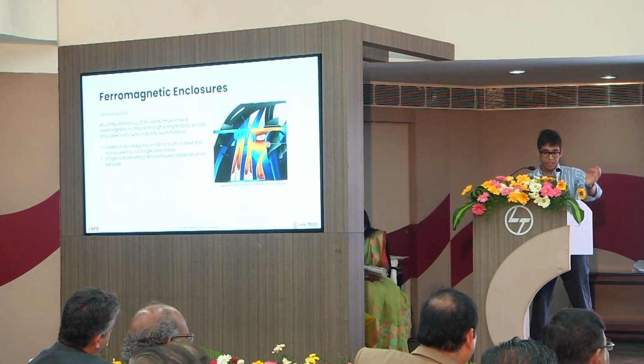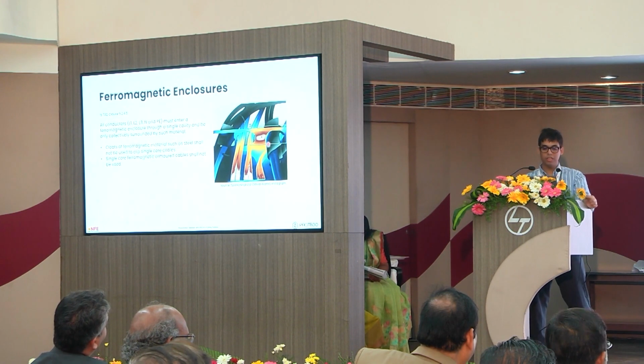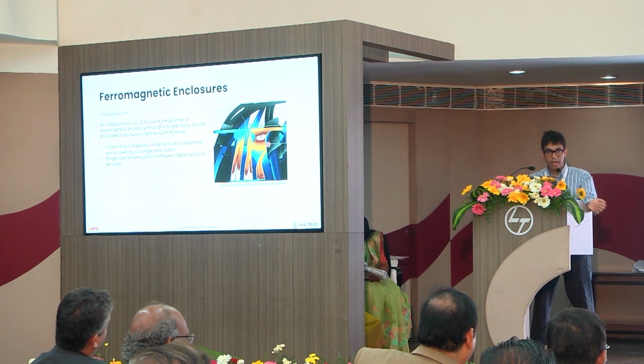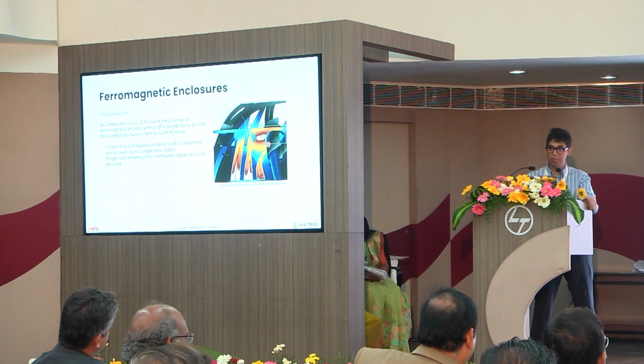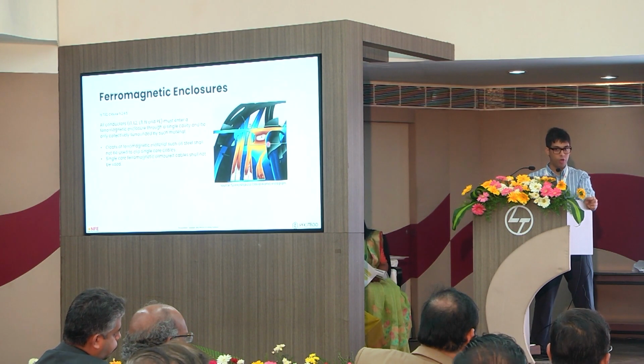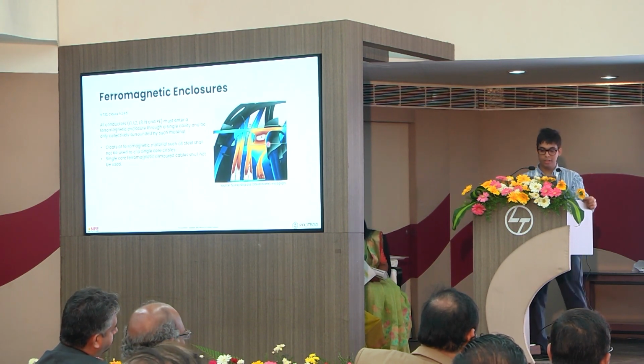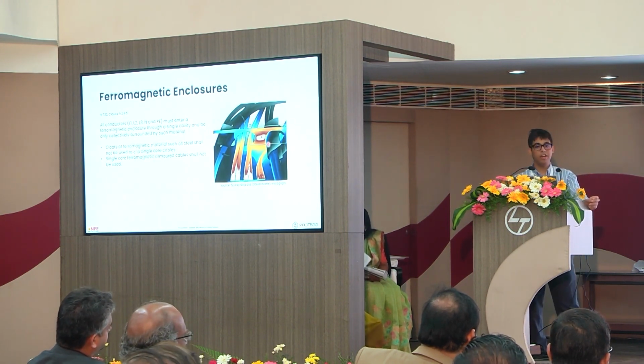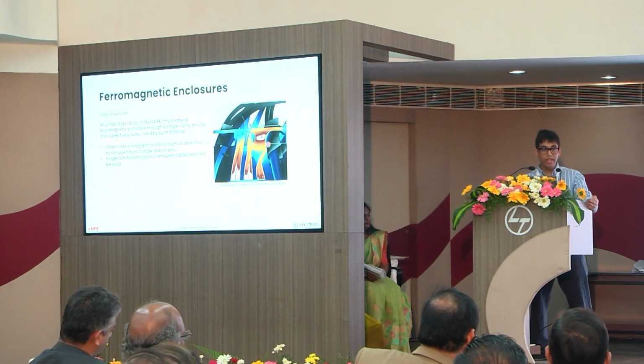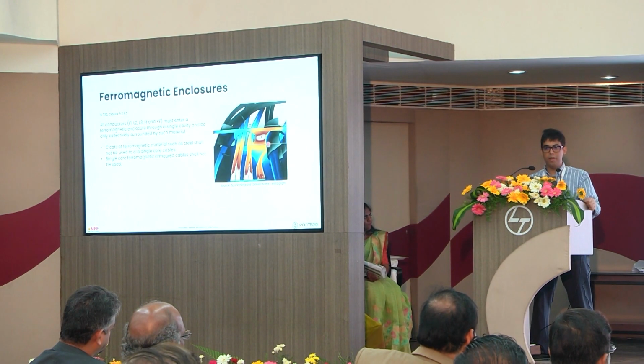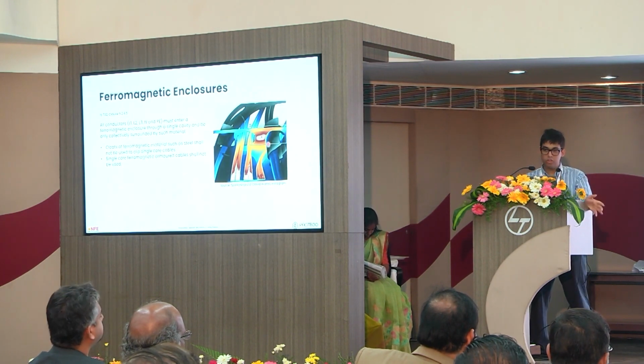And if you have steel cable cleats, you cannot use these on single core cables, because again, eddy currents. Additionally, if you have single core armored cable, you have to use aluminum armored cable, because aluminum is not ferromagnetic unlike steel, so this consideration is not a problem. And if it's a specialist application and you need to gland through multiple cables, you can simply use an aluminum gland plate, as then this is no longer a concern.